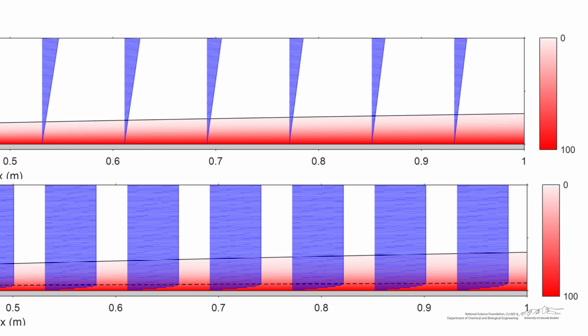Oil, again, is on the top, mercury is on the bottom. Again, what we found for mercury is that the temperature diffused readily into the mercury itself. The thermal conductivity of mercury is really high. It diffused into a region in which the fluid velocity was not even impacted. So it diffused outside of the momentum boundary layer.